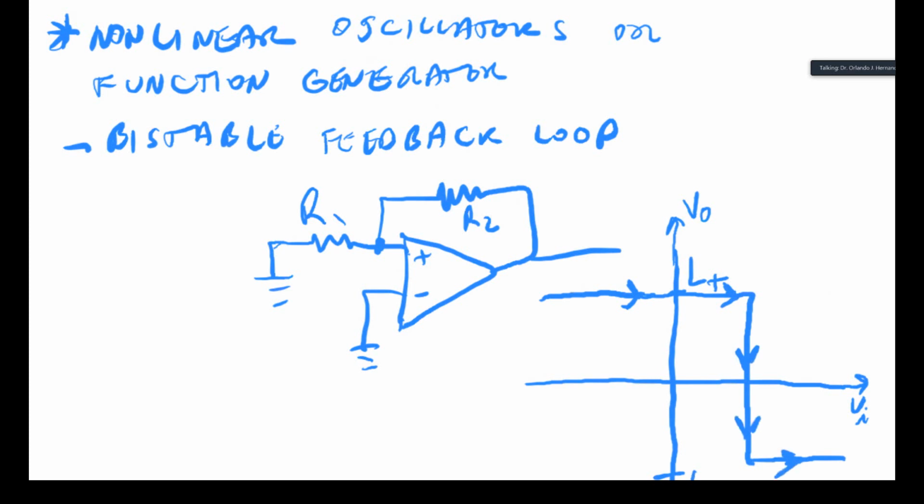Like that. So we can call this voltage here, this is a transfer curve, so it's voltage versus voltage, voltage out versus voltage in, as defined. We can call that the threshold voltage for switching. Okay? And it doesn't matter how much we increase that, it's just going to stay at that L minus.